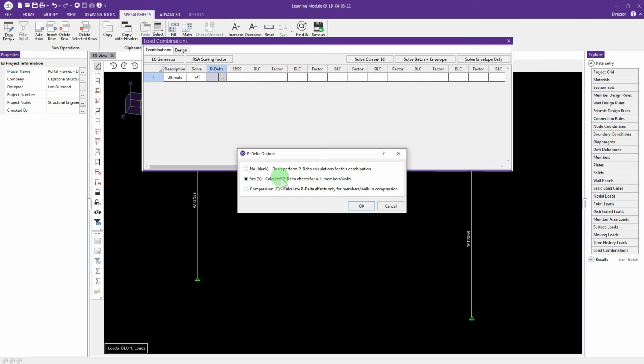If you were in a situation where you wanted to see whether or not you could use some of that increase in tension stiffness to help your model, you can use the yes option. But this option will also implement a decrease for anything that's in compression. So this handles tension and compression changes in geometric stiffness.